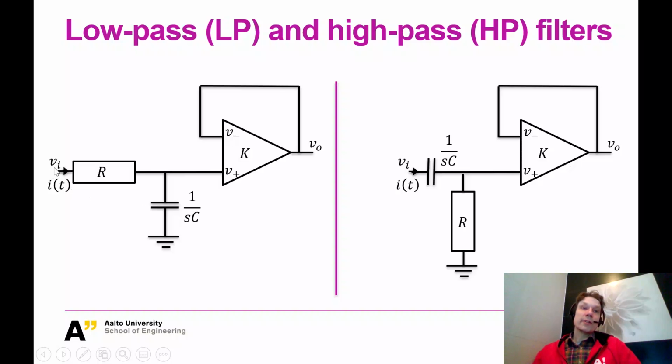And over here you can see that if you have a DC current, it tries to go here. Okay, it cannot go here. It doesn't go here either, because capacitance is pretty much an open circuit. Nothing happens. But then if you have a high frequency, this becomes more like a short cut, and then this leg and this leg, again they are at the same potential, and it follows. So you can also, by reasoning, recognize which is the high pass and which is the low pass filter.